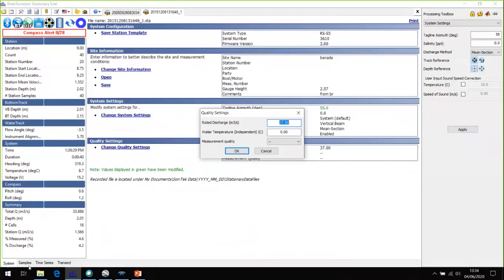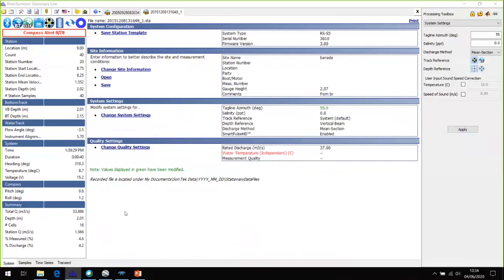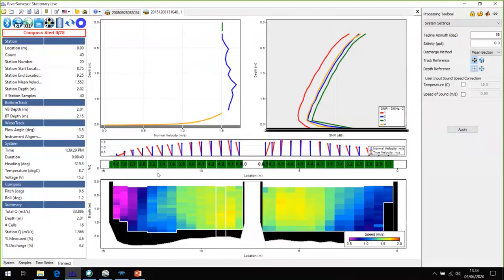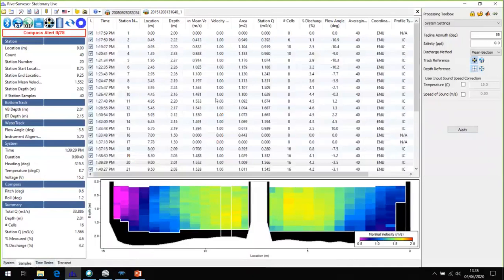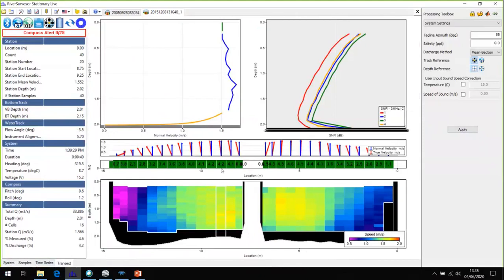You can also view it roughly in there. Sorry. But it's nice to have the graphic, but if you've forgotten while you're measuring, you can view the flow per station in this panel here. So you can start to work out whether you need to chop these up. You want to see, certainly aiming for less than 5, not busting 10%, and also not just percentages, but gradual colour changes are nice too. You don't want going purple to yellow, even if it isn't 5%. You try and chop up the river a bit.